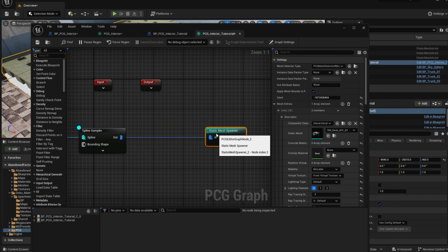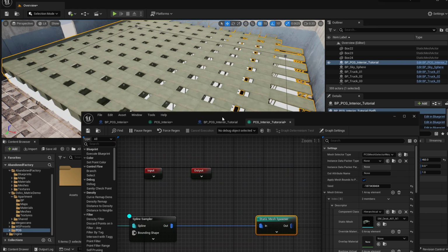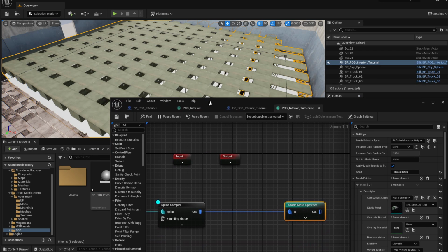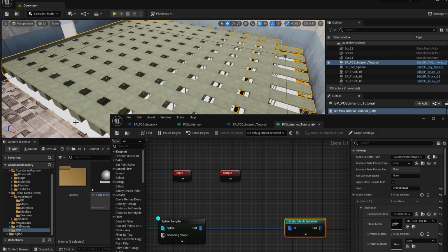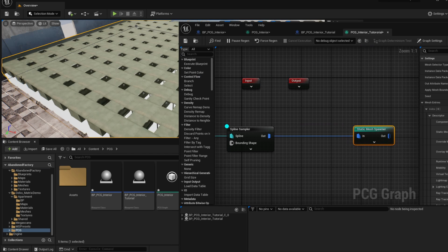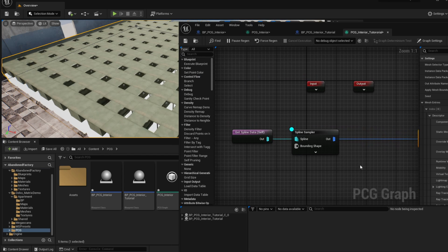So to fix this problem, you will do some pruning of the points. First you need to match the bounding boxes to the static mesh you're spawning to properly indicate which area is taken by this object, and then just prune the results in order not to spawn points on top of each other like it's currently doing. Let's do first our bounds modifier to modify the bounds to closely match the desk that we are spawning.